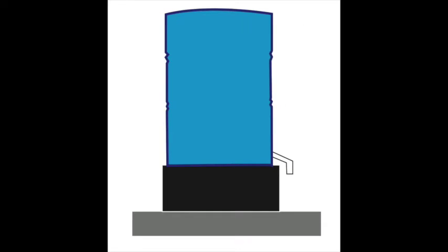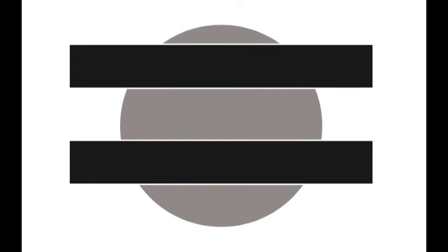We designed our vessel to have a drain on the bottom as opposed to a faucet that you could turn and stop the water. We did this to remove all the water from the activated carbon to make sure that its life is prolonged. Looking at the bottom of our drawing, we have a concrete slab laid underneath the filter. This will ensure that no contaminants will enter the filter or the purified water. The media vessel will be elevated above the concrete slab with a row of bricks. This is a cheap and effective method for raising or lowering the filter depending on the container used to collect the water at the bottom.